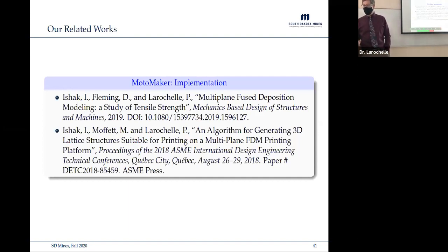And then the temperature of the extruder, is it fixed or programmable? Yeah, that was one of the process parameters that we found in our experiments to be a key process parameter. So that was controlled in real time. We'd have a temperature set point, and then we have a fan and a heater that controlled.